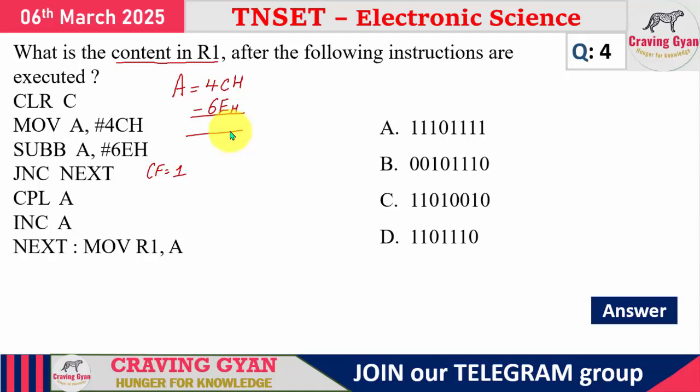If you are not in a position to solve it, you can perform 6EH minus 4CH, then whatever result you get, take the 2's complement of it, and you get the answer. So what is the value of 6E in binary? How do you write 6E? 0110 for 6, 1110 for E.